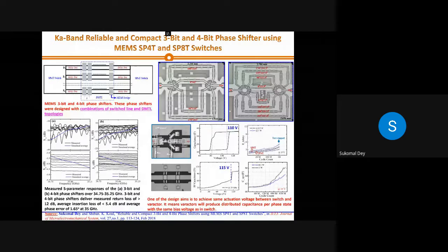But you can see the voltage is at quite a high level, 110 volt, because if your voltage is on the higher side, it means your beam restoring force is very strong. If the mechanical force is very strong, that's why it takes too much electrostatic voltage to come to the snapping position, to come to the connecting position. So that gives you good robustness in your switch.